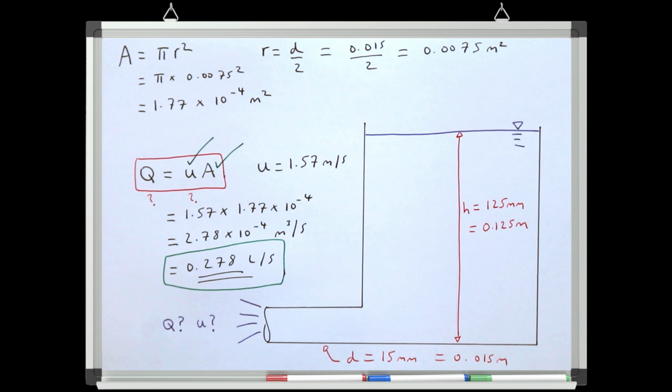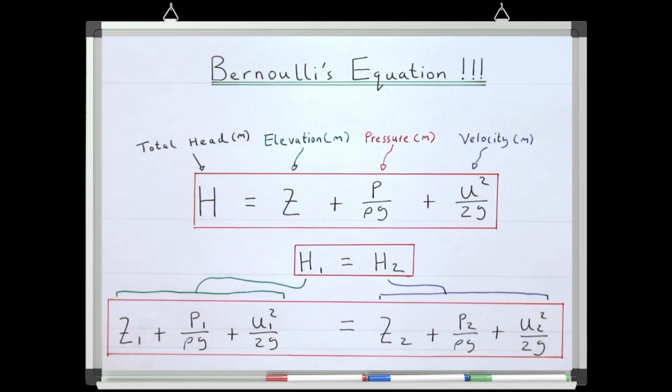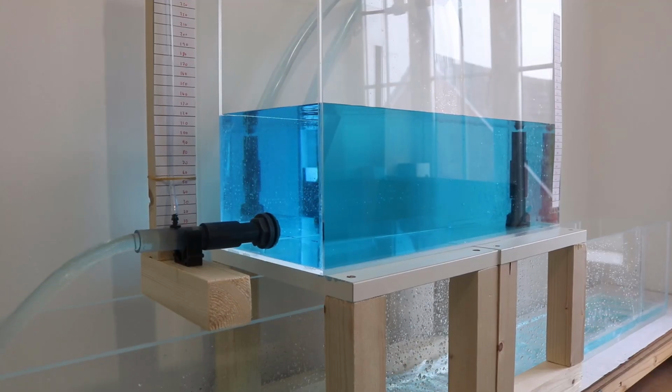This is really pretty close to what our calculation gave us, and would certainly do as a great ballpark estimate of the system's discharge. However, it's clearly not exactly correct. The predicted discharge, where we're using Bernoulli's equation to find the velocity, is about 20 to 25% larger than the actual discharge in the system. Have a think about why the predicted discharge, using the assumption of the conservation of energy, might be larger than the actual discharge in a system like this. We're then going to talk about this fully in lessons 3 and 4.